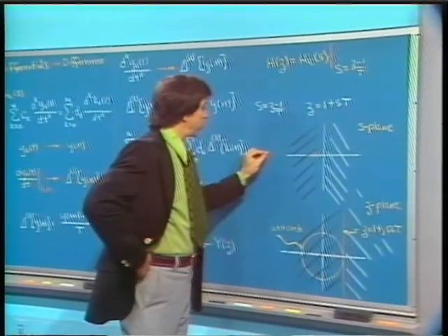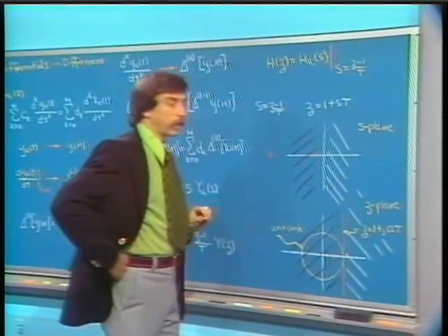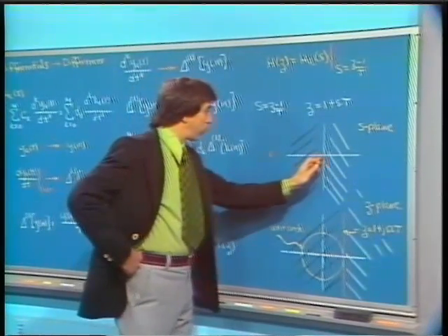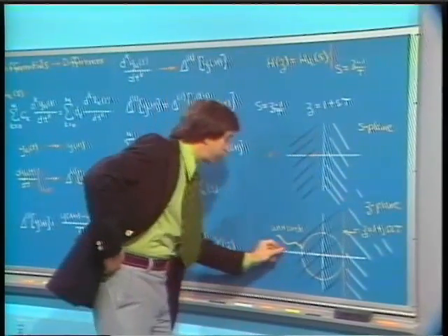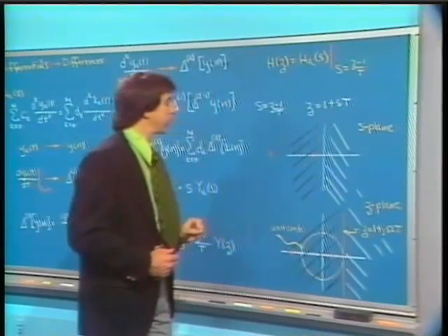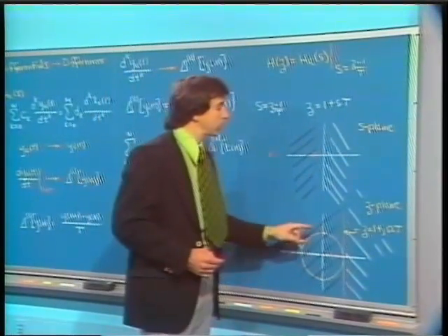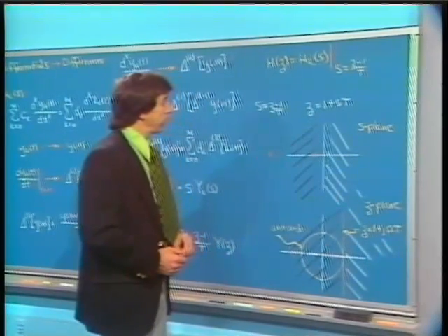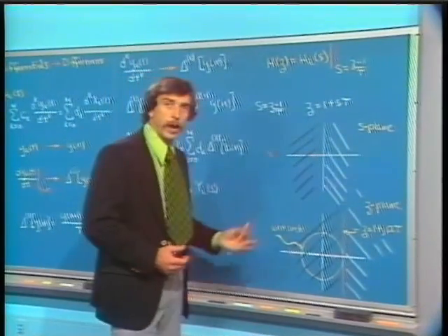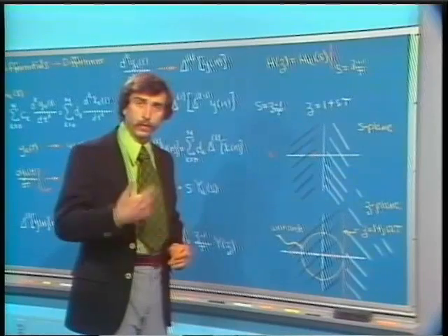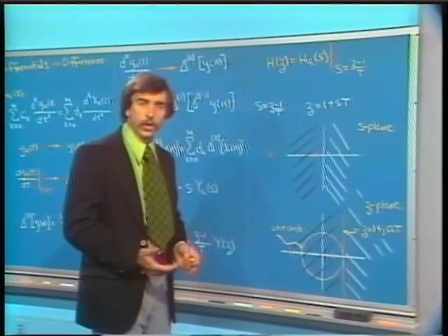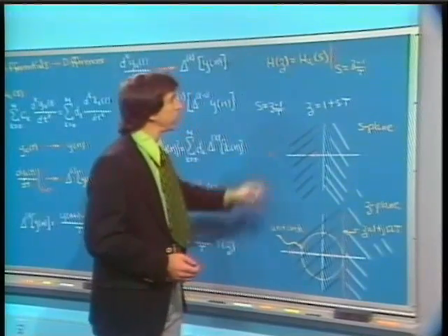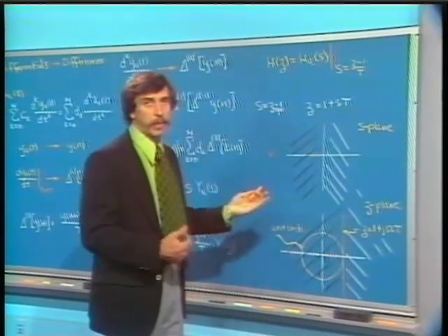However, here's an even more stable analog filter. And if this pole is far enough, is negative enough, then in fact it falls outside the unit circle in the z-plane, and consequently the digital filter will be unstable. That, incidentally, is a well-known property in numerical analysis of forward differences. That is the notion that forward differences are unstable. And this is one way of seeing that by interpreting it in terms of a mapping from the s-plane to the z-plane.